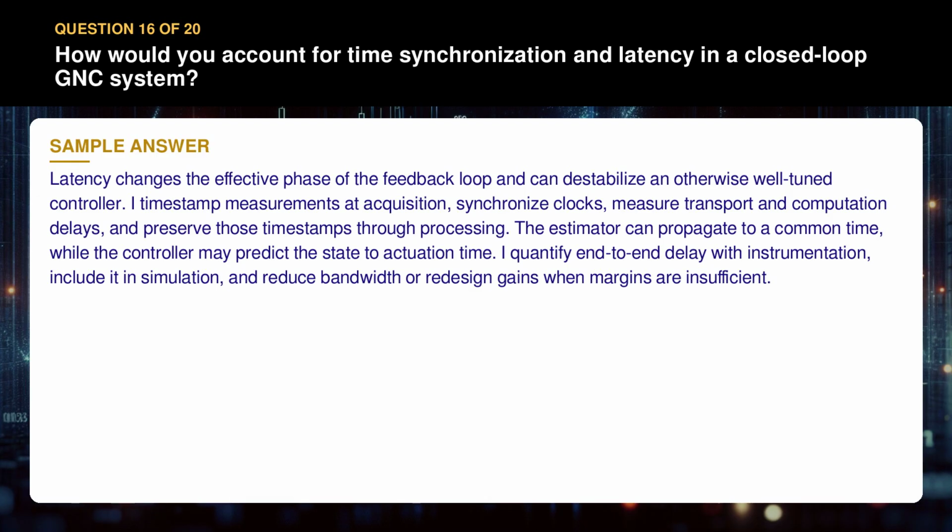The estimator can propagate to a common time, while the controller may predict the state to actuation time. I quantify end-to-end delay with instrumentation, include it in simulation, and reduce bandwidth or redesign gains when margins are insufficient.